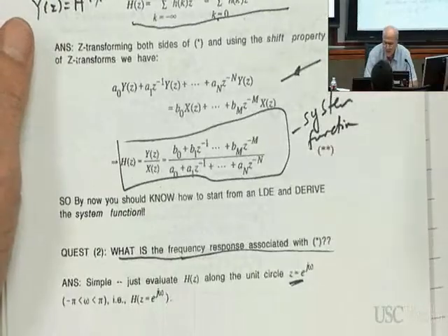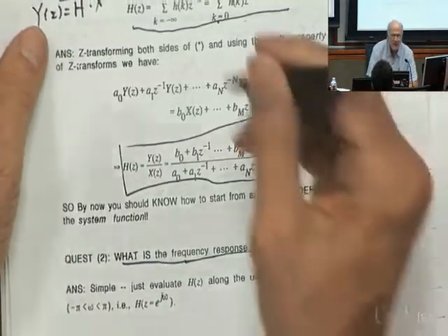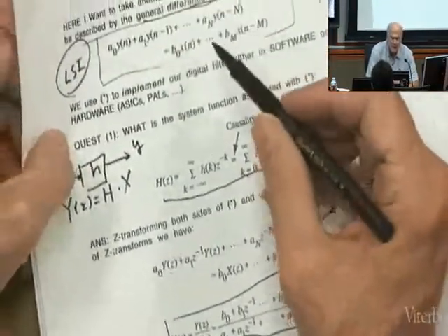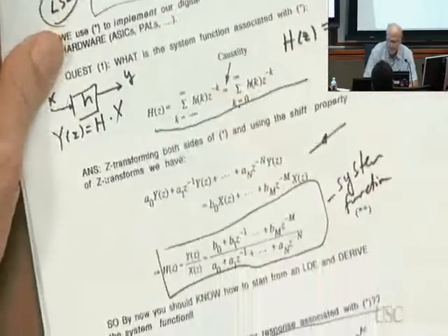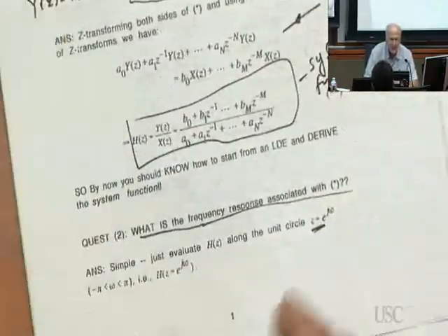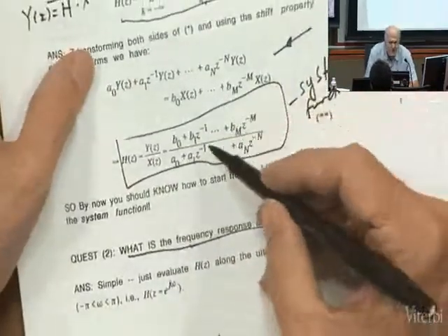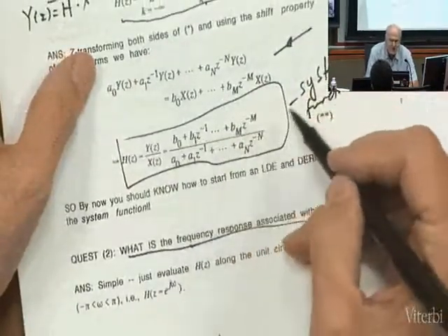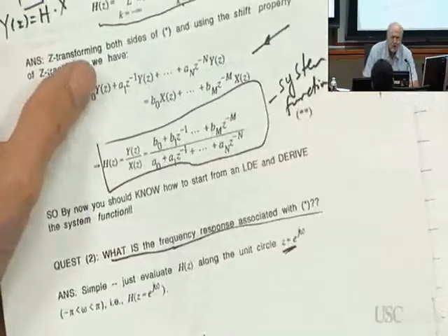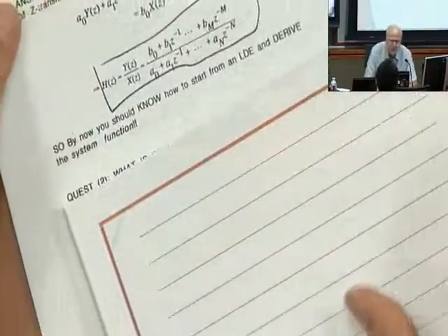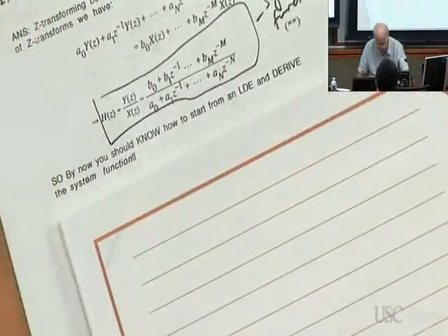But anyway, what I was saying is that if you take the Z transform of this difference equation, as we discussed last time, you end up with this form for H of z. And once again, you see these coefficients, B0, B1, in the numerator, and A0, A1 in the denominator. The way the Matlab filter function works is very simple once you get used to it.